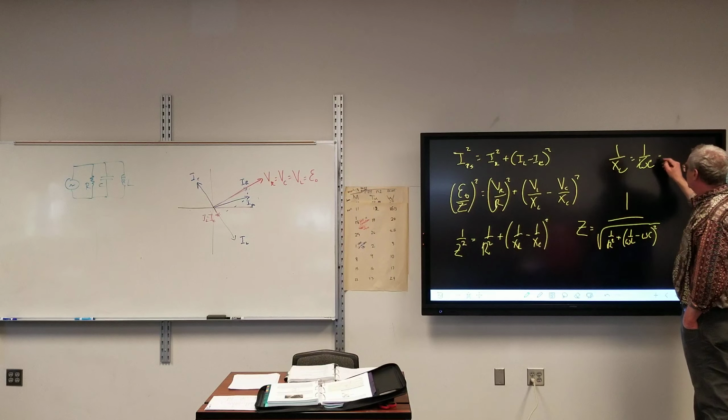All right, let's do some numbers. Let's figure out some phases. So again, we'll make this 60 ohms. We'll make this 30 millifarads. And for this, let's see, so it's going to be omega L. Let's make this 20 millihenries. I think that'll work. Let's find out.